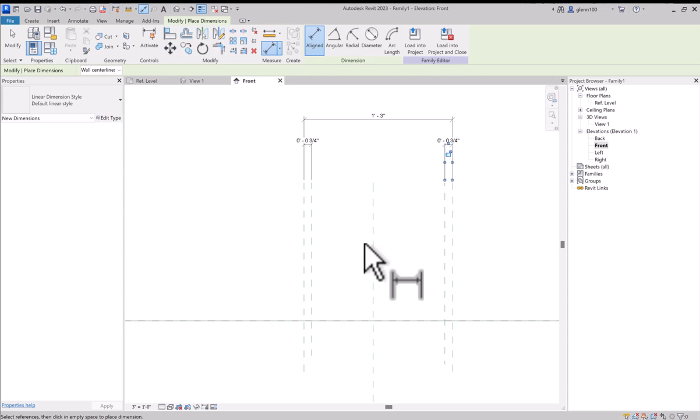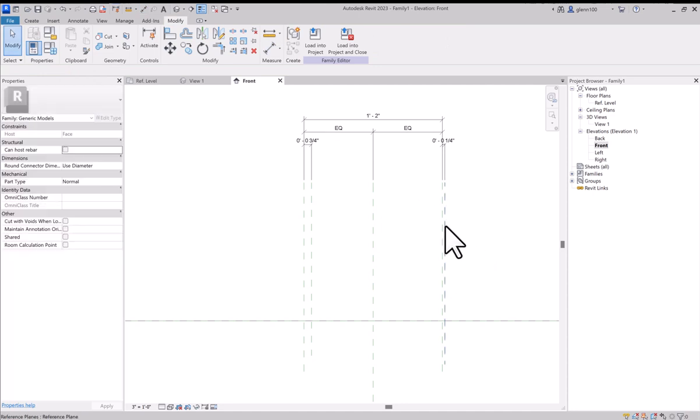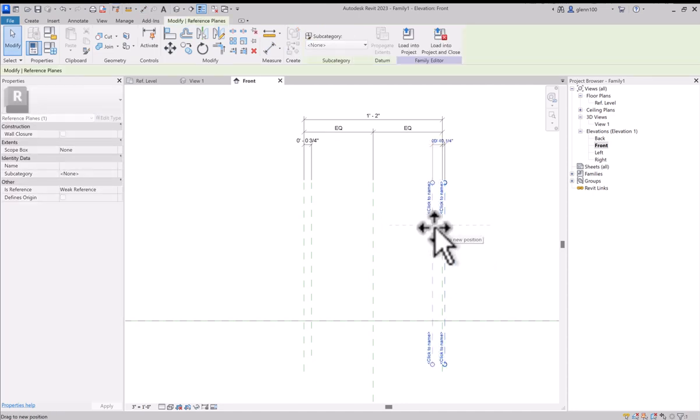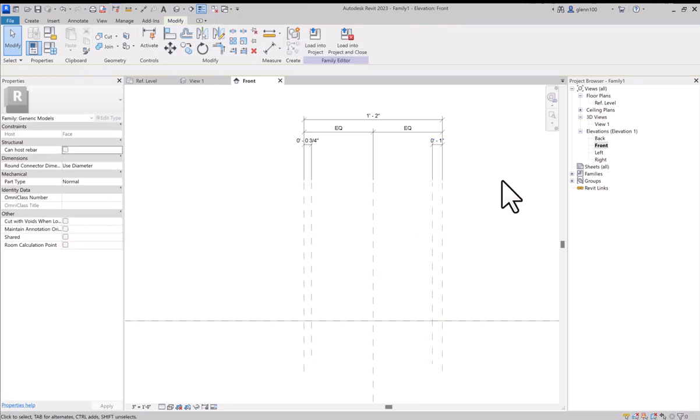The other thing is that I want in this model this line and this line to always be equal distance from the center point. So when I insert it, it will always be the center of the object itself. So I'm going to put another dimension in here, from here to here to here. Okay. And this, I'm going to hit the equal sign and make it equal. And notice it pulled one over to the other and kind of messed this up, but that's okay. We'll fix it. Okay. So I'm going to move this back to the inside of this for right now.